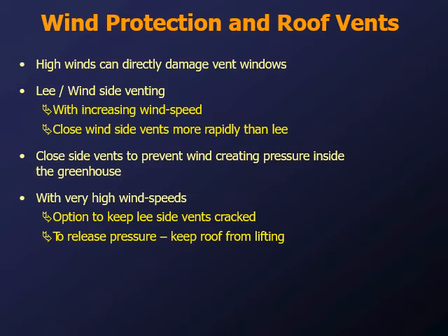And if you have a real storm coming in, oftentimes you kind of have to think, right? Computers are great for running a greenhouse, but they don't always know everything. We have situations even here in Niagara where a storm can whip in within minutes. Depending on your computer systems, they often have a delay, so many minutes before the vents move, to prevent constant movement so they don't wear out. If say your delay is 5 minutes, 5 minutes is more than enough time for a storm to whip up and winds to go from almost nothing to extreme. And that's when you get real wind damage.